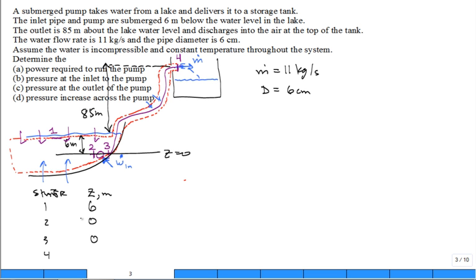85 plus 6. All right, that's good. The speed of the flow in meters per second at those locations. The cross-sectional area for 1 is very large, the surface of the lake, but it's a little bit below the top surface of the lake. So what is the velocity of the water cutting into the control volume across surface 1? Approximately 0. Negligible speed.